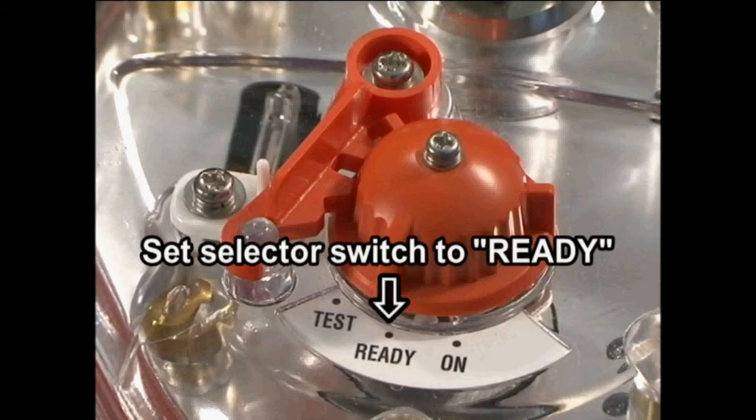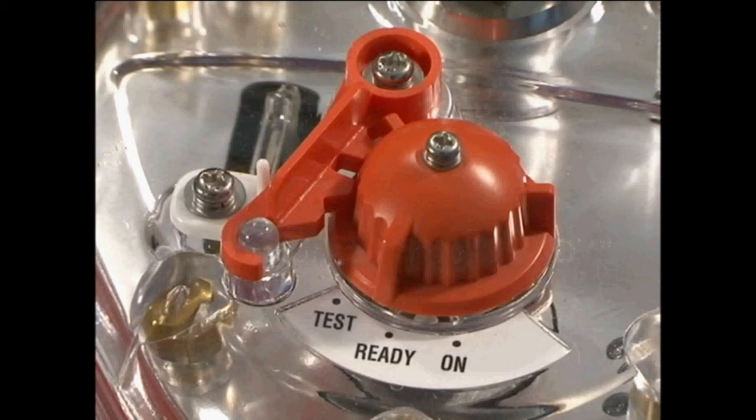The selector switch has three positions: ready, test, and on. In normal operation, the switch is always set to the ready position. In this position, the EPIRB is released and begins transmitting a distress signal automatically after its water sensor detects water.